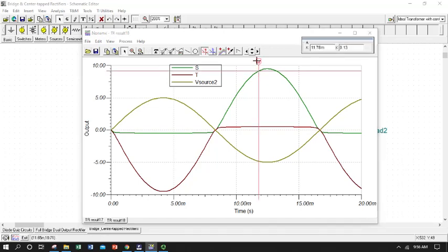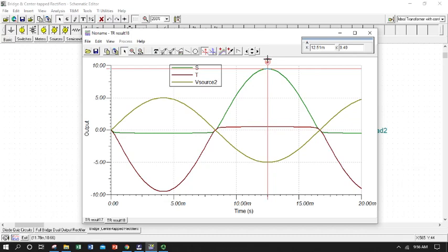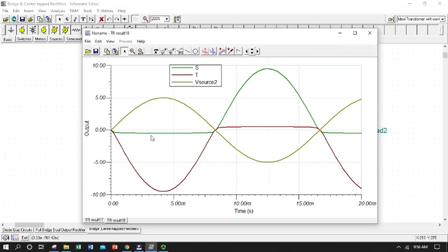Your measurement tool is specific to the curve you click it to. So 9.5 and 9.5. We had about a 0.5 volt reflected for our diode forward bias voltage on the diodes we selected for this simulation. So this is pretty accurate. Instead of having one reduction, we're having a reduction on each side. So our total peak to peak is showing that reduction by 2 diodes. So that is making sense for us given the way things are running through